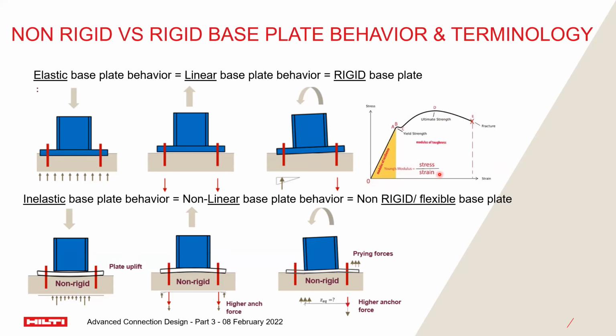The base plate behavior may be nonlinear under some loading conditions also. Nonlinear behavior generally requires advanced computation methods to analyze. As far as the profile of the plate itself, we can see from the free body diagrams that the plate deforms under the applied loads and does not maintain its profile.